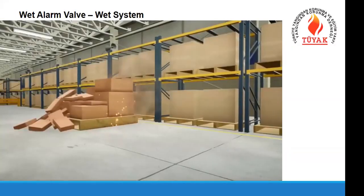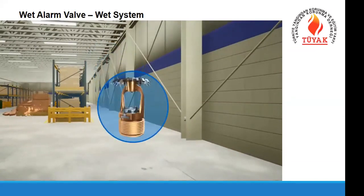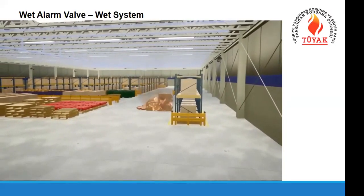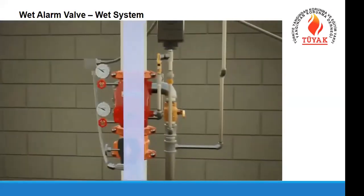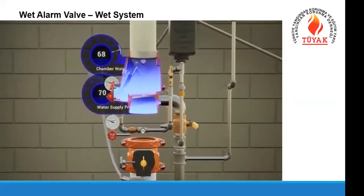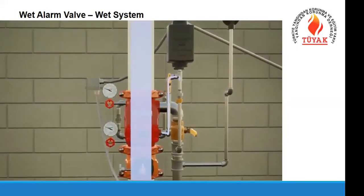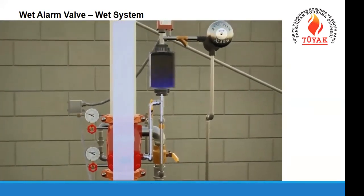A fire has started in the building. As the fire grows and the heat reaches the rated temperature, the sprinkler will activate. Since this is a wet system, water is already in the pipes, allowing immediate delivery of water to the fire. After the sprinkler activates and water flow is established, the clapper is fully lifted off the seat and the alarm ports are exposed, allowing water to enter and fill the alarm line. If the system is equipped with a retard chamber, there will be a slight delay as the chamber fills before activating the water flow alarm.